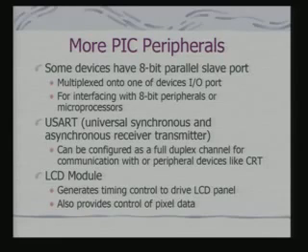Now, what we are talking about here is an 8-bit parallel port, typically for interfacing with 8-bit peripherals or microprocessors. And these ports are typically multiplexed onto one of the device's I/O ports. Now, why is this kind of port required at all? Simply because there are lots of peripheral chips available in the market which were targeted for interfacing with 8-bit microprocessors, and the PIC wanted to have a facility to use them as well. So, this 8-bit multiplexed parallel port provides for that.